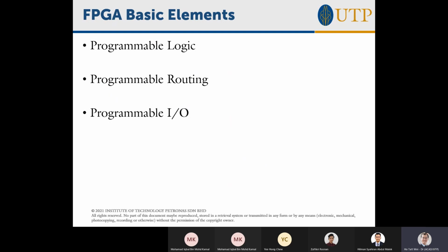I mean that if you want to implement a ping pong player game, you can. You write the Verilog RTL, you click the button, and you specify the placement, which pins are connected to the monitor and all that kind of stuff. Then the software tool does the synthesis, the placement, the routing, and generates the serial bitstream, which is nothing else but the SRAM bits.